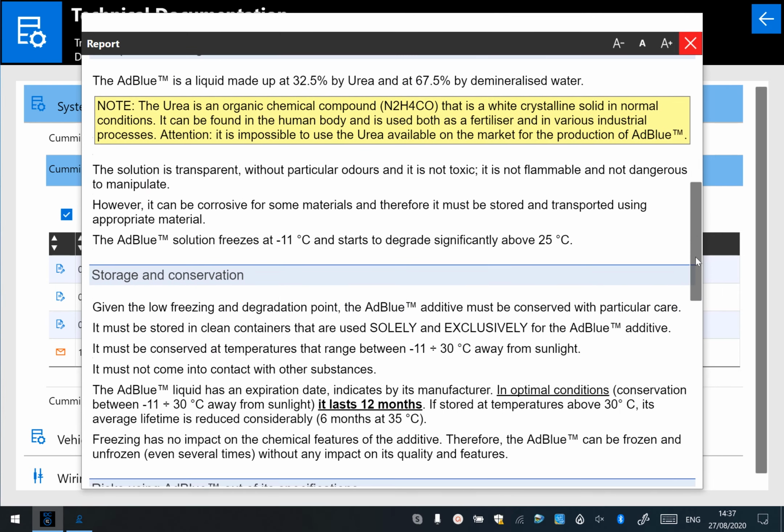On some vehicles, you'll know yourself, you've got maybe a few hundred sensors. So there's the opportunity to filter that list. It'll put it in an alphabetical list. You can then pick only the sensors you want to look at and create your own list. From that, you are then able to do up to a 30-minute record. So you can take the vehicle out and run it for 30 minutes and record those sensors, and once you go back to the workshop, you can start investigating it further.